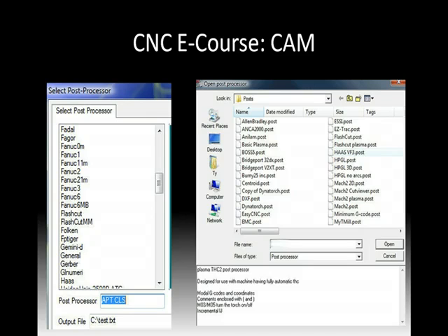Well, there's different post-processors, as you'll see here, because there's different CNC machines, and each one is somewhat unique in how it likes to move, and so these post-processors make it very flexible. You can spit out G-code for all these different types of machines. So you'll see a number of CNC controllers as well. But you'll see on the right, those are plasma cutter post-processors, and the ones on the left are milling machine post-processors.